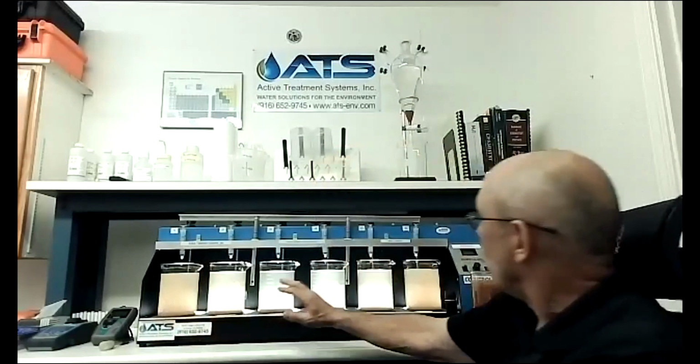And it's possible when I'm operating a system that I would find the dose that'll be right between this one and this one, and even lower it some more, rather than just shoot from the hip and add plenty of a good thing. That will get the job done, but it will cost you more money. We risk putting polymer in the environment because we're using more than we should. So the negative consequences are, it's just not worth it.